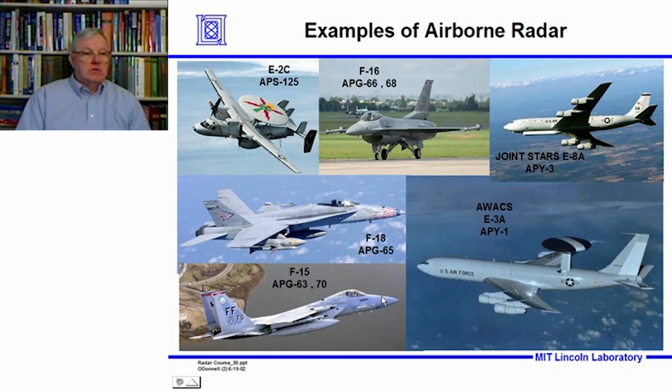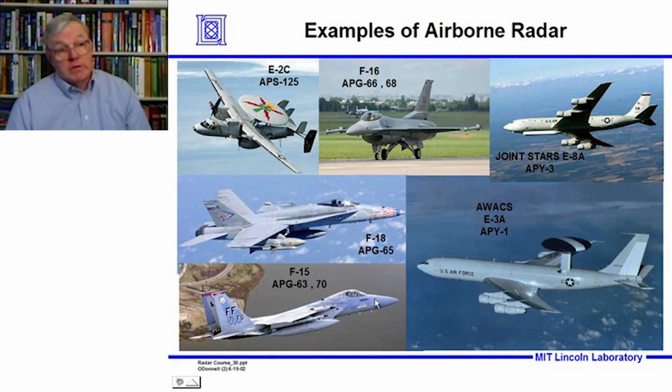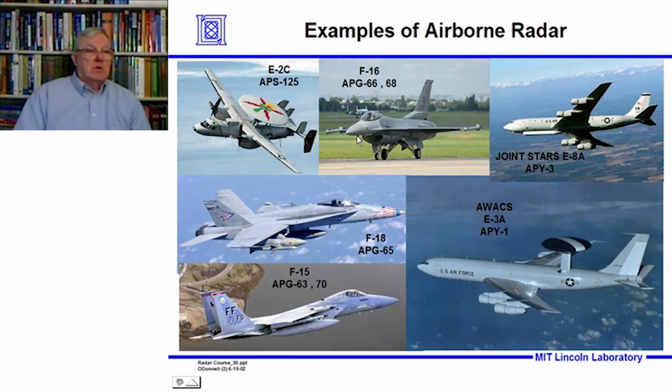And because of the size of the nose, if a man is 6 feet tall, you can expect that the aperture in these radars is pretty small. And for what you've learned about antennas already, that means the frequencies have to be relatively high to get good beam width. So in these noses are radars that assist the pilot in seeing targets in front of them.